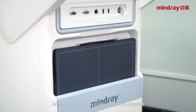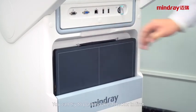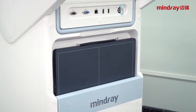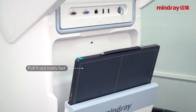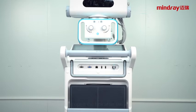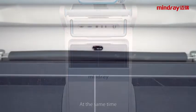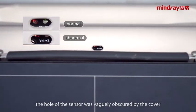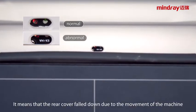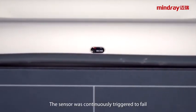When the detector box cannot be opened and the lock switch sound cannot be heard, you can try pushing the detector in first when you trigger the sensor of the detector box. After hearing the unlocked sound, pull out quickly and then open the detector box. If you still cannot open the box after the above operation, and at the same time the hole of the sensor is vaguely obscured by the cover, it means that the rear cover fell down due to the movement of the machine. The sensor was continuously triggered and failed.